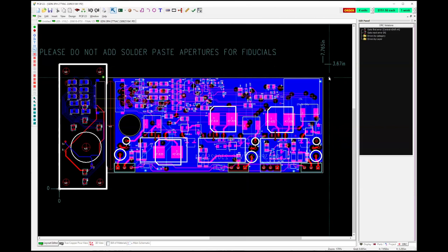Okay, so here's one. If, for example, I place a footprint for a DIL socket, the BOM does not reflect the price of the expensive processor chip it should hold. Is there a way around that? Yes, you have to either make the part using the correct DigiKey information, or you can have Snap EDA make it for you and use that part. If you just place the footprint on the board, it won't have any part number information. It won't be intelligent per the schematic. It's just a footprint.